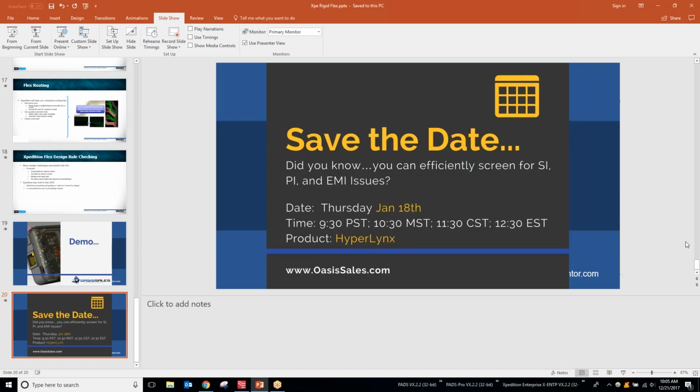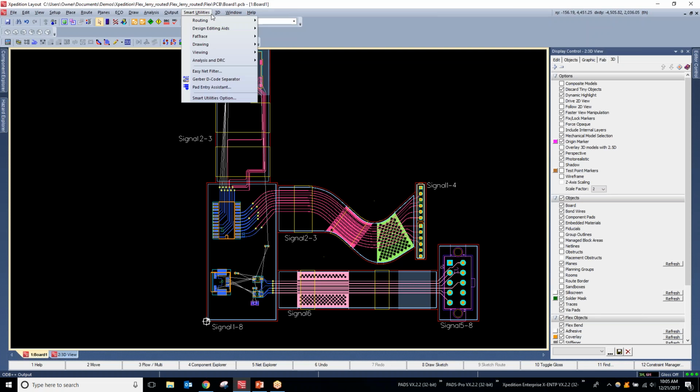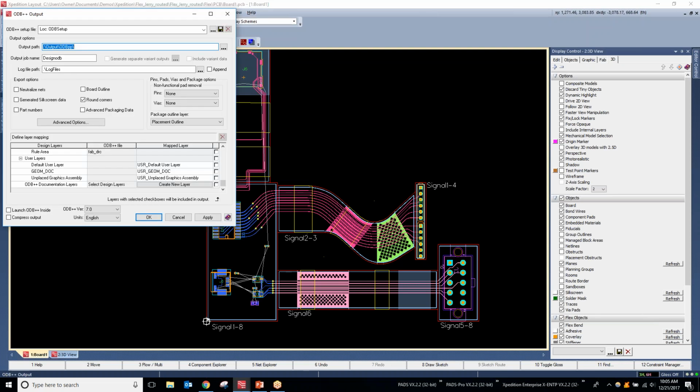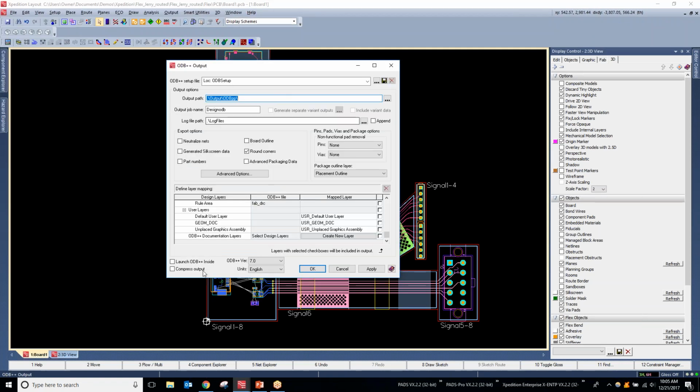All right, so it doesn't look like any other questions are coming in. Oh, actually, I just saw Randy again. Hi, Randy. Can you output flex data with Gerbers and NC drill instead of ODB++? Yes, absolutely. There's no issue with that. I just like to highlight ODB++ because it contains all of the data in basically one package, very simple to understand.